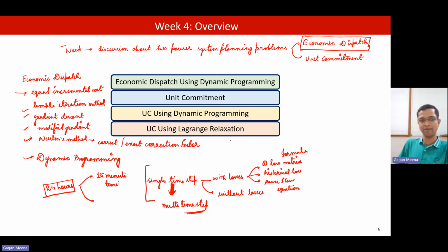The market clearing happens in each 15-minute time block. So for 15 minutes, the generation has to hold its generation. The schedule has to be maintained, except for the ancillary services requirement, which may be there. In India, it is 15 minutes. For 24 hours, we have 15 into 4, for each hour we have 4.